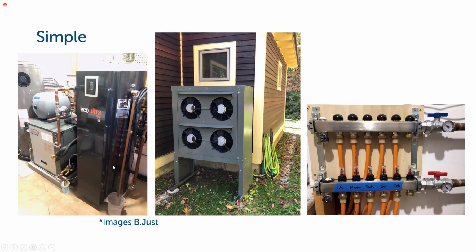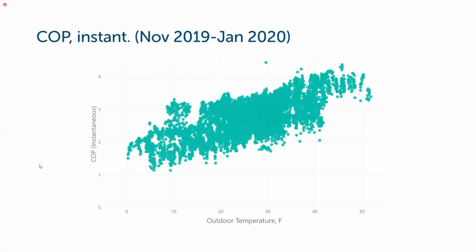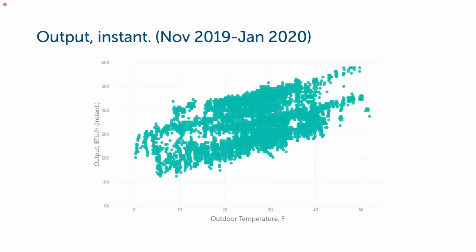So what you're getting is insurance to make sure that you have enough hot water at a sufficient temperature for the distribution within the house, no matter what the outdoor temperature is, no matter what the heat pump can do. But when you're looking at the total number of hours that you're going to be below its ideal performance range, it's pretty negligible. But you have the backup baked into the system design.